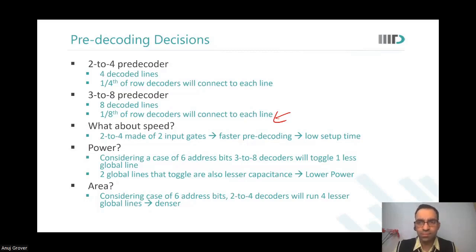Sir, but if we increase the number of stages, the delay should decrease, no, sir? Depends. Again, logical effort result. Logical effort, yes, sir. So there is an optimal number of stages that you would want to keep. Yeah, true. So you arrive at that. That is what we will use. Okay, sir. In the course project, some of the teams would be involved in designing this address decoding. So you will have to do this logical effort analysis and arrive at an appropriate architecture there.